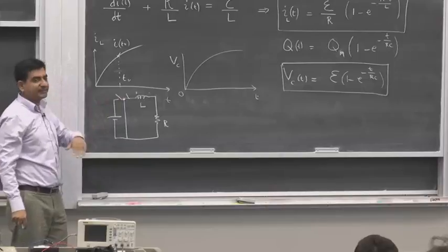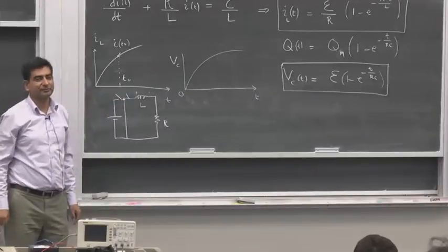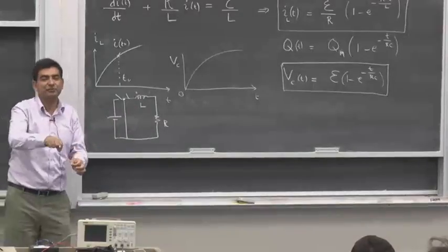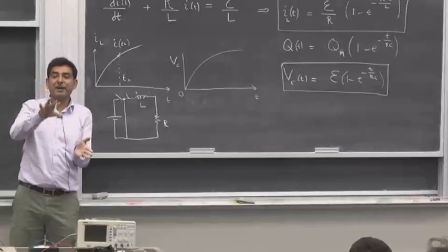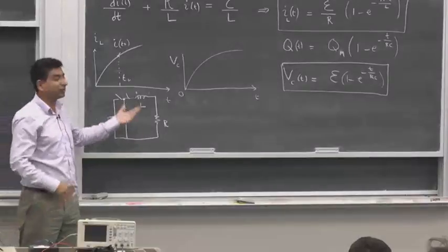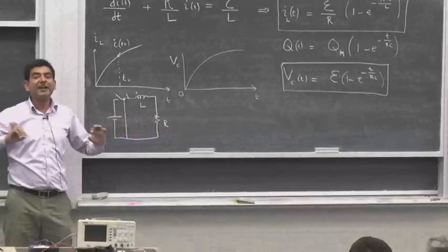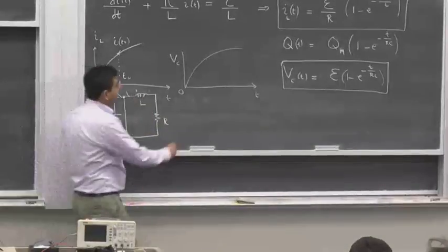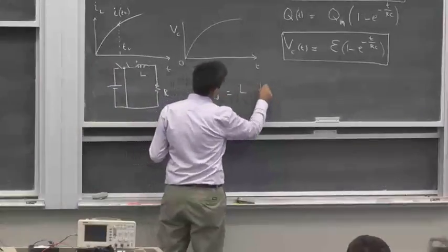So this battery is disconnected, but at the same time you open another switch. So the current through this inductor is going to rapidly go down to 0. So there was a current flowing through the inductor. Now you would like the current to rapidly go down to 0. Current cannot flow because the switch is open, the circuit is not closed. That will create a large voltage change in this inductor, because the induced EMF is given by L di by dt.